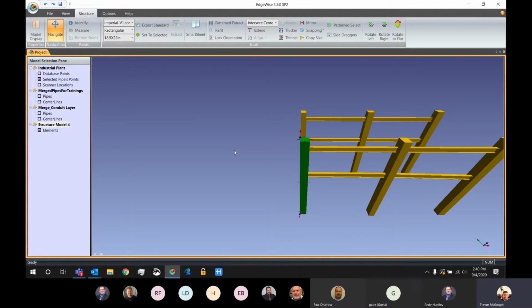If it finds the object, it'll do a true mass extraction, fitting each one individually to the point cloud to get you your as-built conditions. Think of it like an intelligent array tool that instead of just doing a blind copy and paste 10 times every 10 meters or 10 feet, it'll actually leverage the point cloud data to do individualized fits.